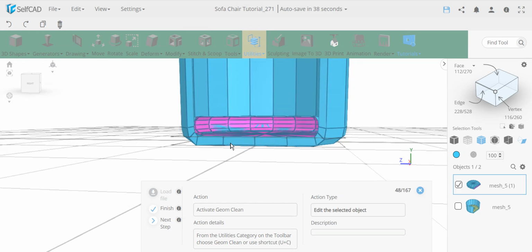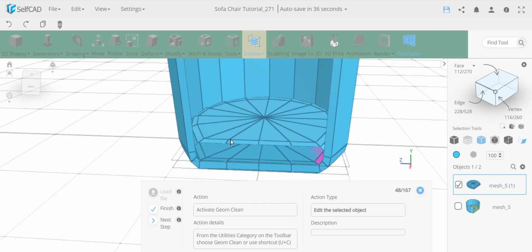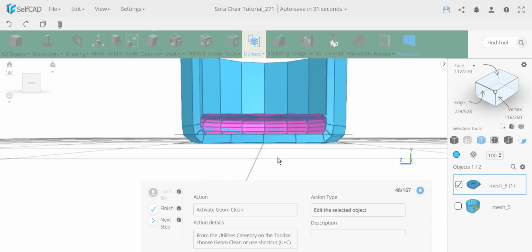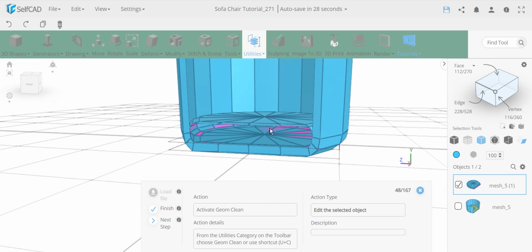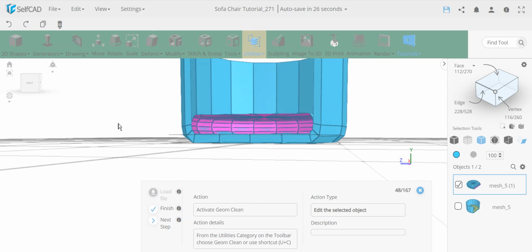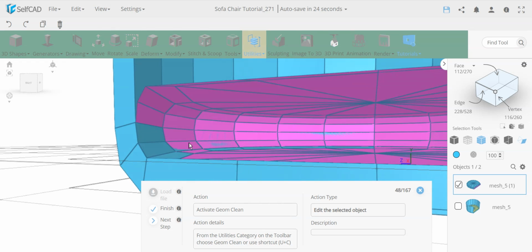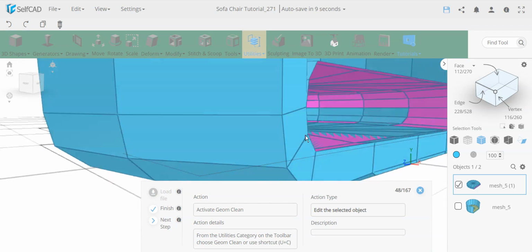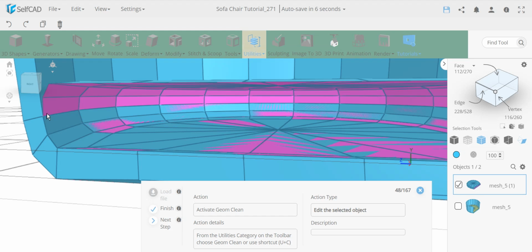Now once this is merged, what you see over here is pointing correctly. You see the top is pointing outwards, and you cannot see the bottom from this because it's hidden in the same place, but basically the entire inside is here. The thing here is, if you count the vertices, when you merge this, you have two sections merged, and you need to remove all of these vertices over here where they connect. I counted them, and you have basically 13 vertices that need to be removed in order for this to become watertight, complete together without gaps.